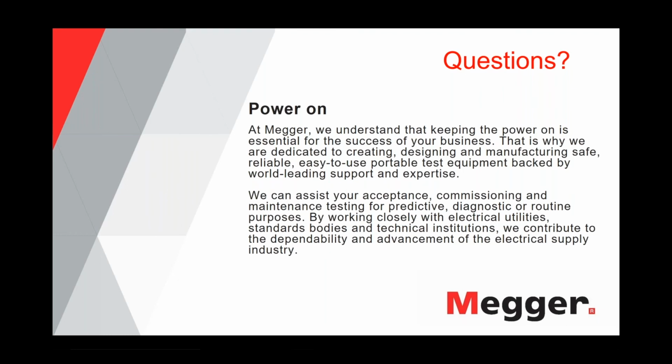All right, excellent. Henning, what should be the test step duration, and how long do you hold on to the voltage for each step? Well, the test step duration is defined by the number of test points you will set up for each test voltage. And typically, you want to have at least 5 test points per voltage step.